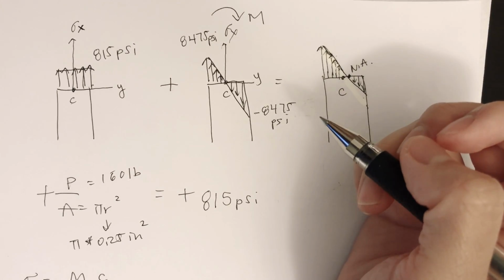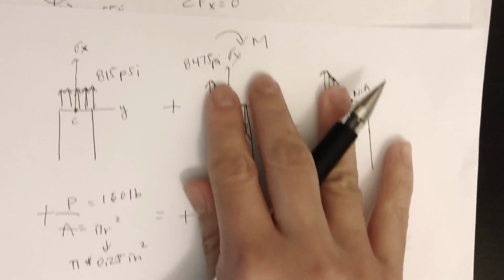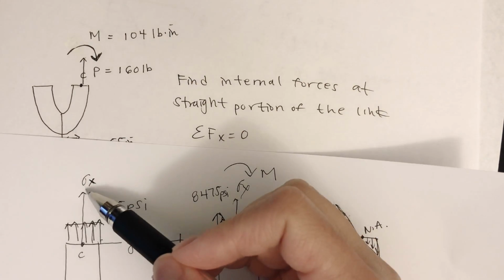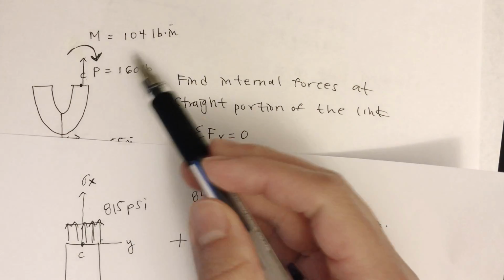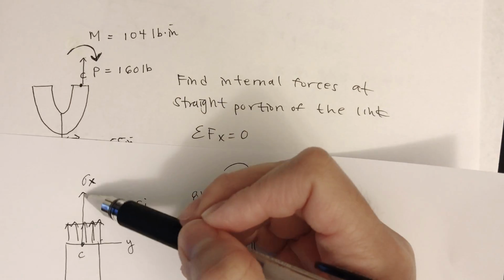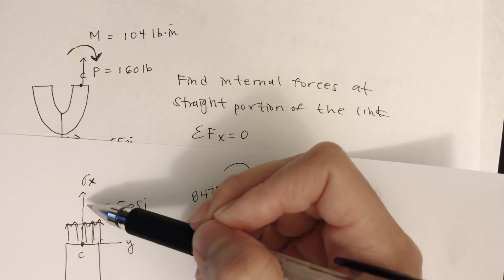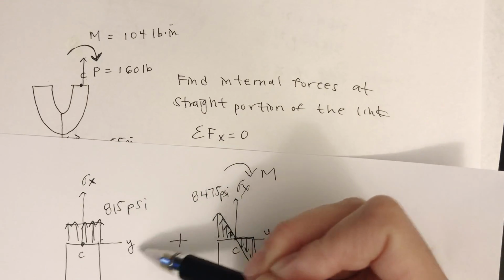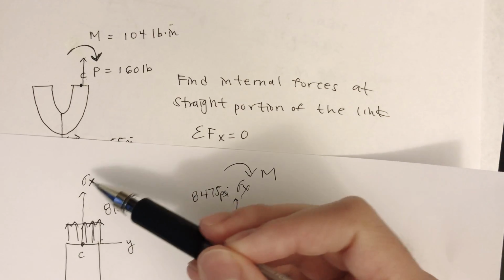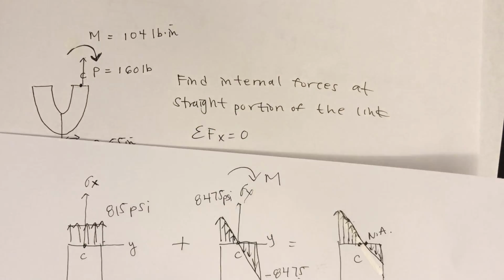Okay, notice that, again, the axes. So here, the stress axis is parallel to the load. So the load is upwards, so the stress axis is vertical. Okay, and the distance axis, y, is perpendicular to the stress axis. So the stress axis is parallel to the load.